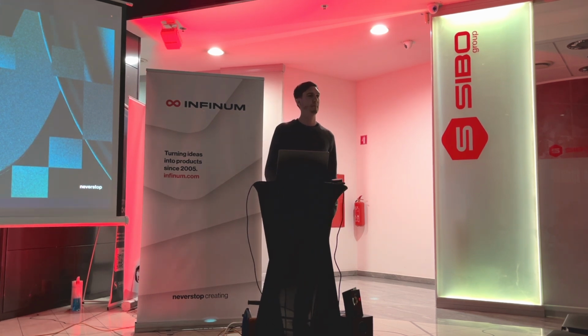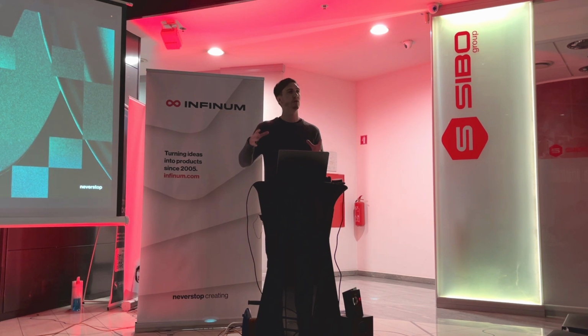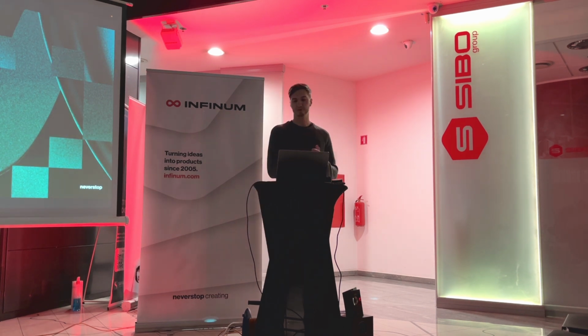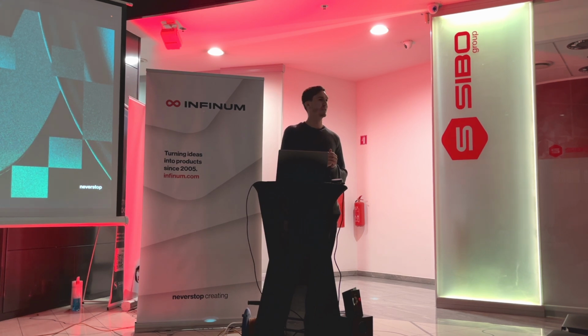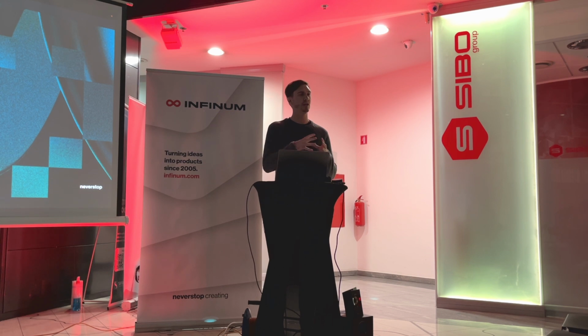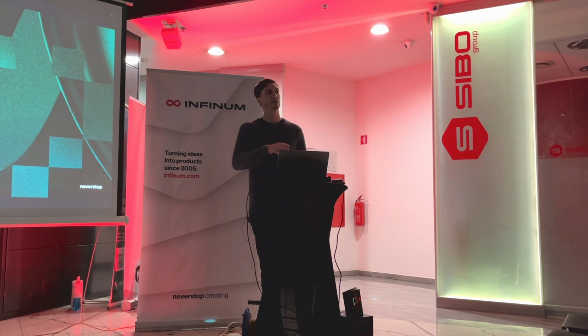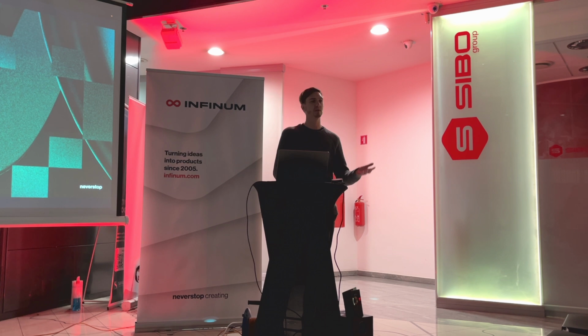When you test this on a real device, can the manufacturer send you some sort of box or something you can test? Yeah, do you mean like the actual infotainment screen? Yeah, that's a really good question, sorry to repeat it. If the manufacturer sends us any proper screens that are used in the car or the entire system, yes, we have something called a test bench, which is essentially the entire infotainment system. That's exactly the same as in the car, but this thing is just not connected to car ECUs. So you cannot get car signals, but the entire screen, the exact hardware is the same. So you can test stuff more properly there.